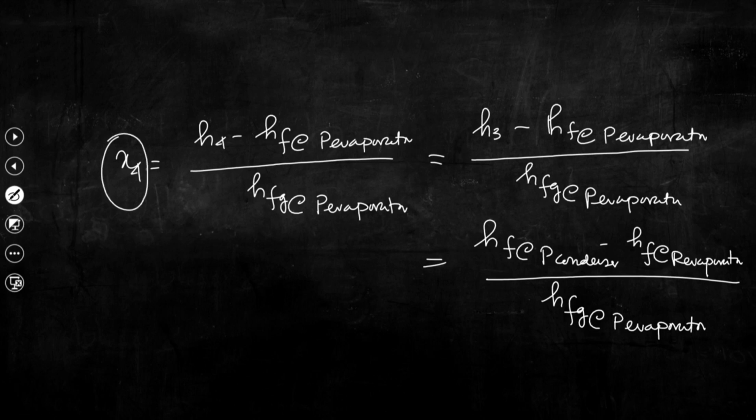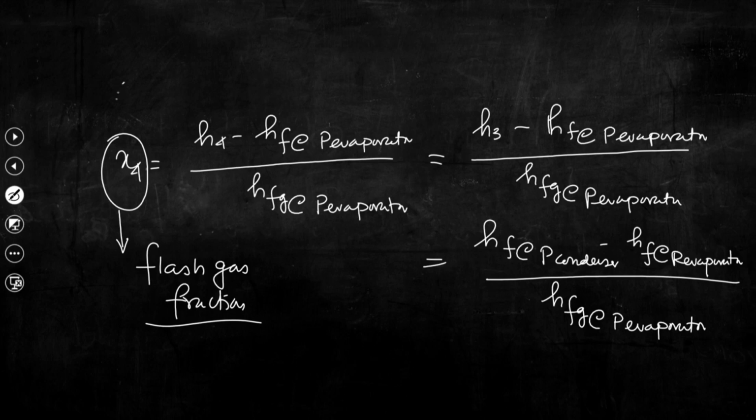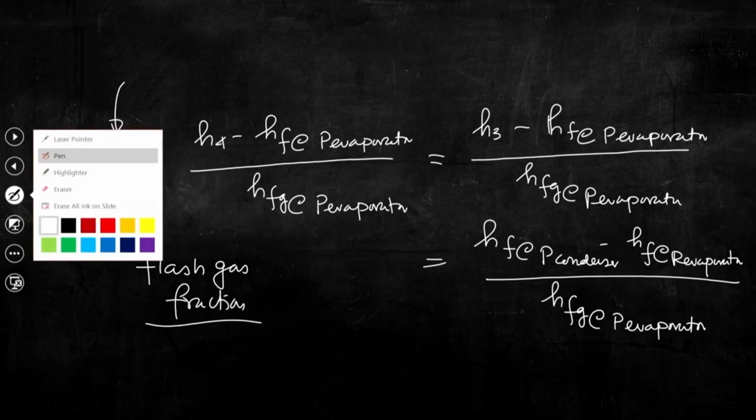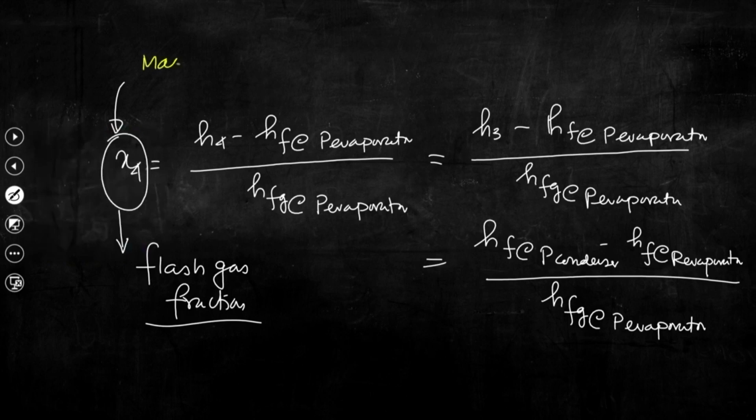So, this X4, this quantity is very important and it is known as flash gas fraction. What does it mean? Basically, the mass fraction of liquid in this liquid vapor mixture.